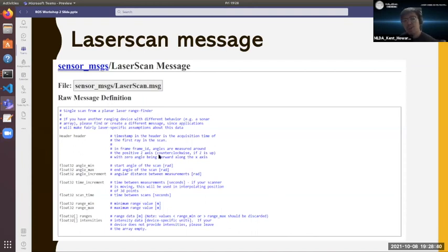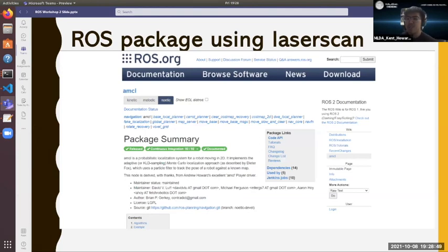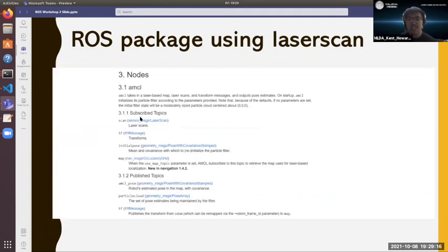So what would happen if we do this? What's the benefit of standardizing everything? Well, take an example of AMCL. AMCL uses a complex algorithm. As an undergrad, I find it difficult to code it myself. I would need to spend a whole week dedicated just to properly code a fully functioning AMCL program that's up to par with the existing ones. But I don't have to do that. In fact, these nodes are made to accept the exact same laser scan messages, irrespective of your brand of LiDAR, as long as it supports ROS, of course.